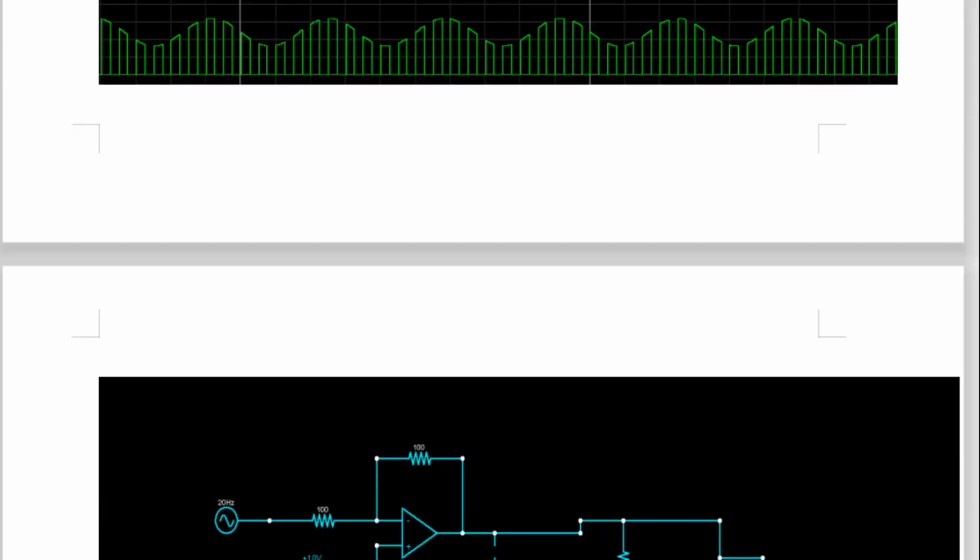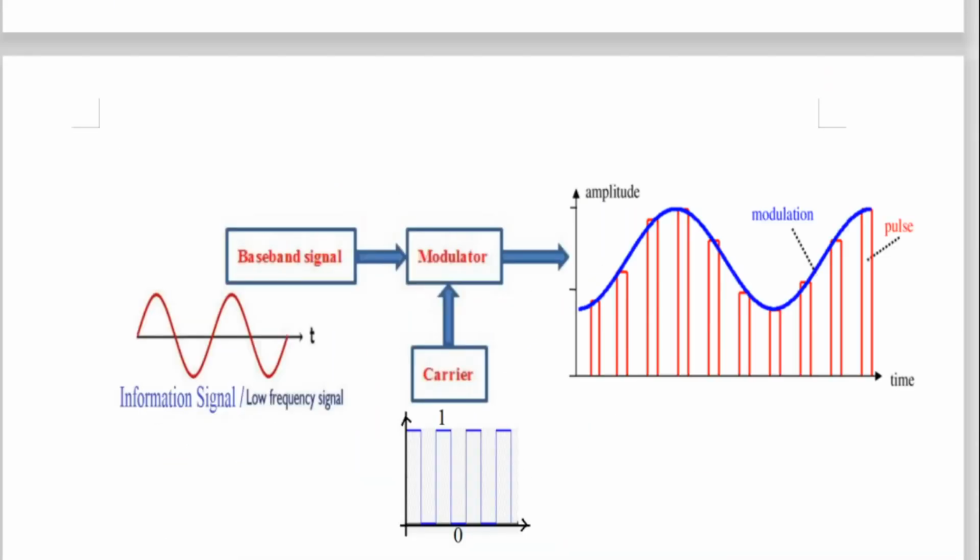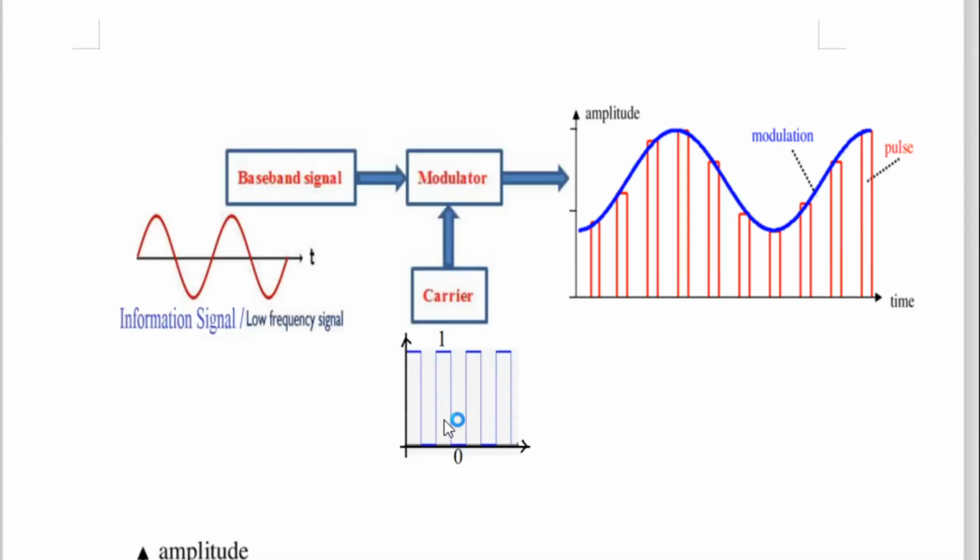But in the earlier case, see the block diagram of the previous one. This square wave has high frequency only, with HVL as logic 1, suppose 5 volt or 12 volt. LVL is logic 0, but this 0 is not going below the x-axis. It is 0 volt only, and therefore it is called single polarity PAM. So here LVL will remain 0 only. It will not go in minus.